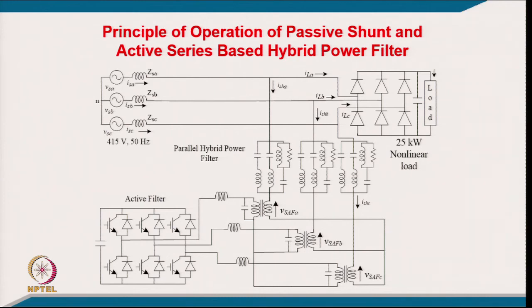And this is typically quite a popular topology. In this case, it is a kind of voltage fed, so we have a non-linear load, but a major amount goes to the passive filter. We connect in series with this a small rating, 3 to 4%, series active filter, so that this avoids the resonance, and the other is it makes the variable harmonic compensation. So, you can inject an adjustable harmonic voltage in such a manner that this sucks the entire harmonic current of the load, and becomes quite effective.